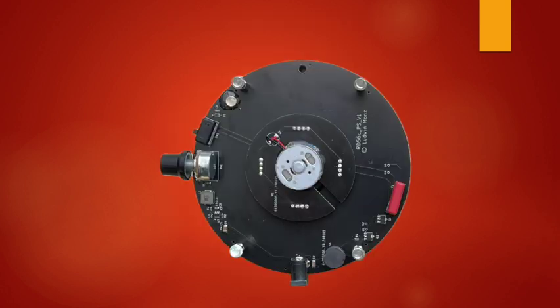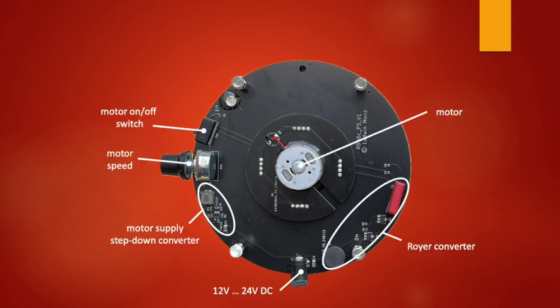This picture shows the power supply board. SMD components were predominantly used on this board in order to increase the rebuild reliability and reduce the soldering effort. Only some components, which are only available in through-hole technology, have to be soldered by hand. In the middle of the board, you can see the motor that turns the display board.